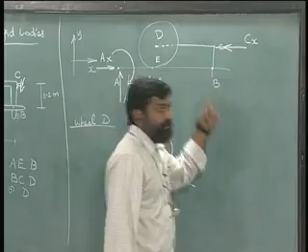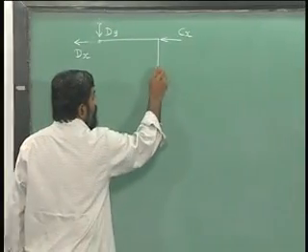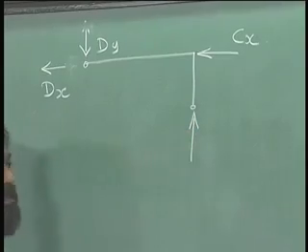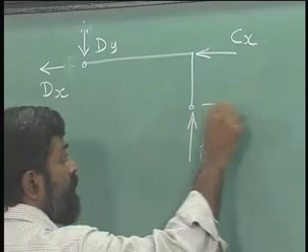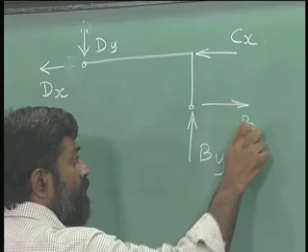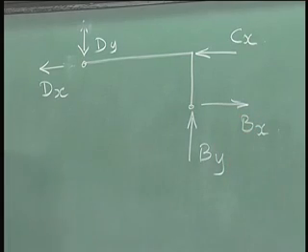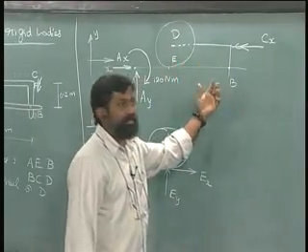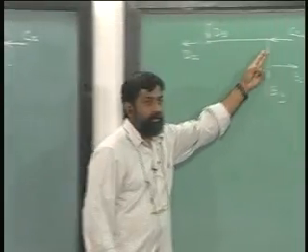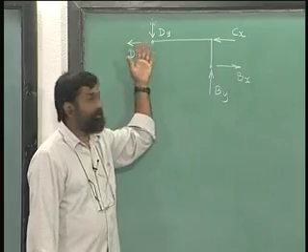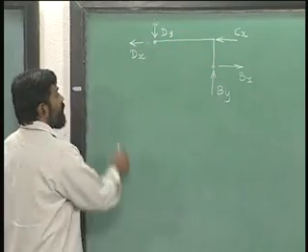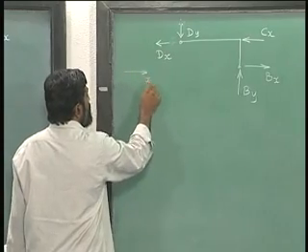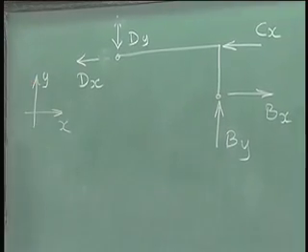At B, we will have a restraint in the vertical direction and therefore a force appears. There is a restraint in the horizontal direction, which means there is another force Bx that appears. Are we complete? The answer is yes, the mass we have here is negligible, which means we have completed the free body of BCD. This is x direction, this is y direction.